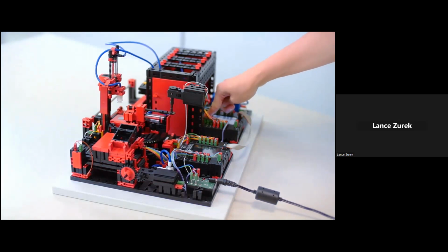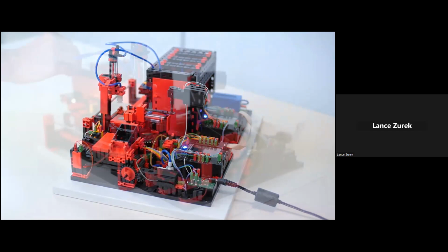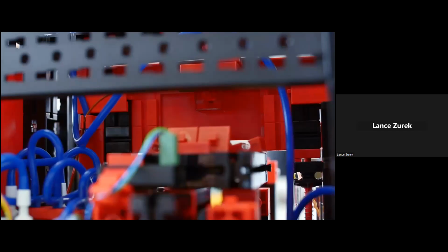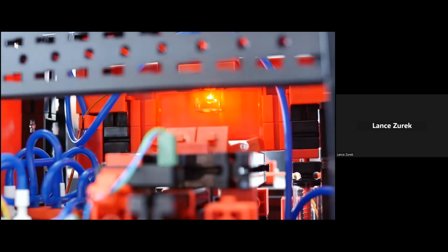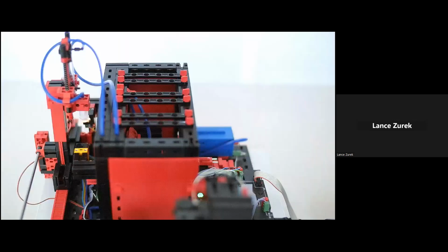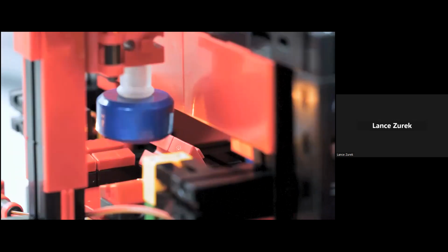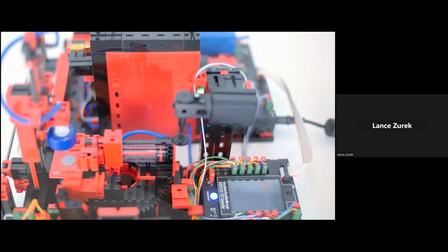The dimensions for this model are approximately 20 by 14 by 12 inches, and it has a weight of just about 11 pounds. Again, the standard version of this model is the 24-volt version for use with the PLC of your choice, with once again a relay board for motor polarity reversal and both a multi-pin connector, again 34 pins with a grid of 2.54 millimeters, as well as additional PCB terminals with push-in connections for all inputs and outputs.